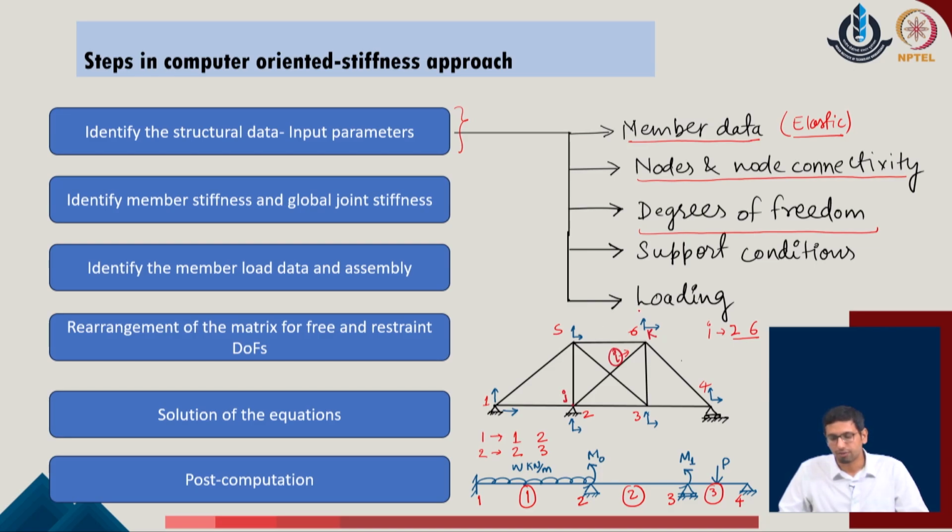And at the end we need to define the loading condition of the given problem, which includes any kind of loads which are active directly at the respective joints, and any kind of loads which are active on the spans of the given members. Corresponding to this information, the code should be able to understand the contributions of the individual loading vectors of the given system.